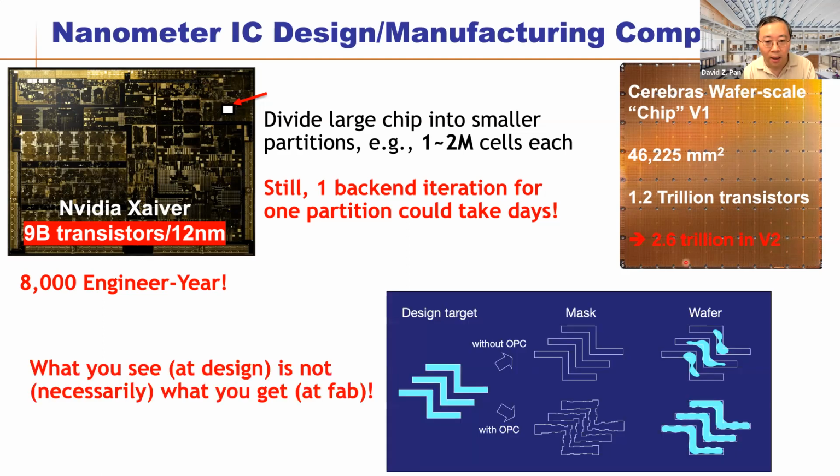Most of the time when you talk to circuit designers and say, oh, we finished the design, they say, we have a bunch of GDSII. They have a bunch of many layers: the transistor layer, the metal layer, vias, contacts, and so on and so forth. Those are a bunch of rectangular shapes.